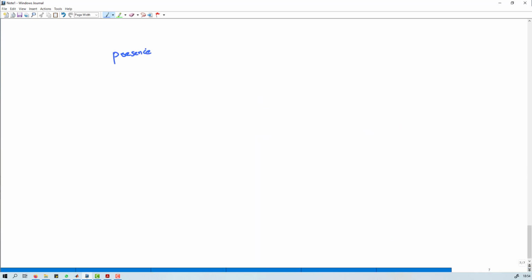Whenever there is a zero available in the numerator, it has to cut the negative real axis. Whenever it cuts the negative real axis, the phase angle will be equal to minus 180. From there you can find the magnitude, and all the remaining information you can easily find when you equate the phase angle to minus 180.